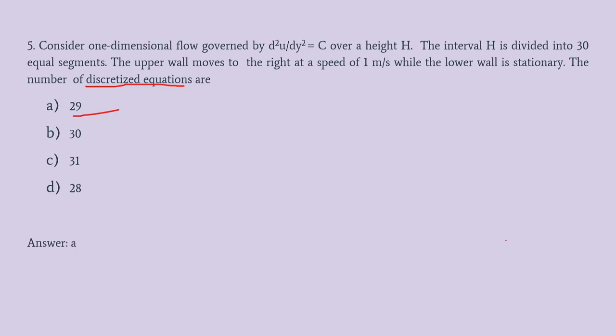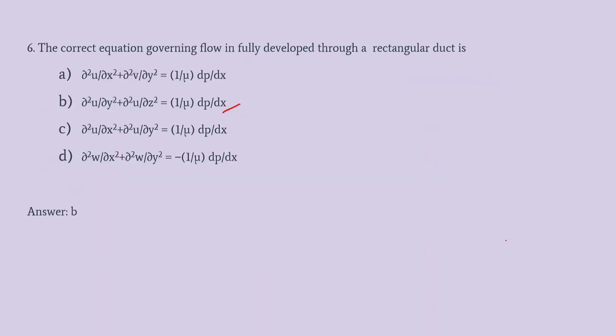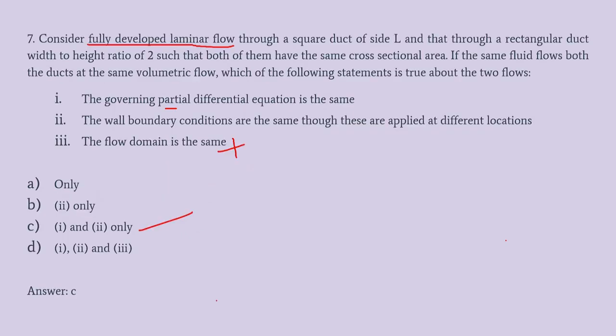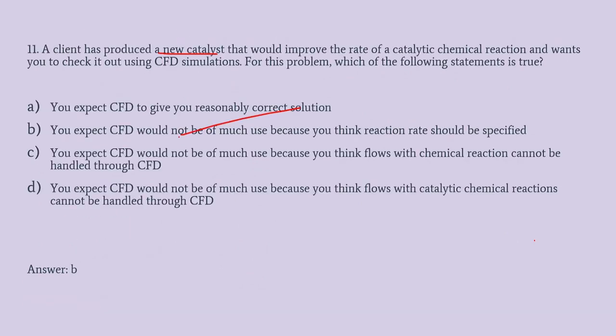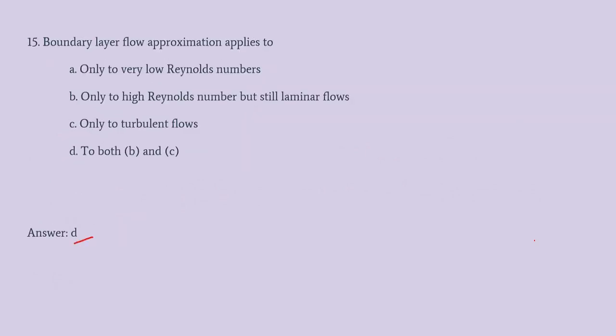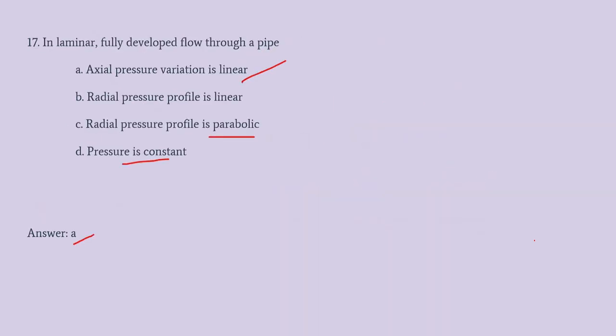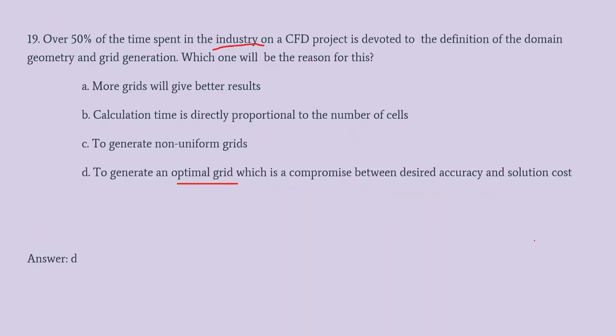So how to generate a mesh? What I have shown is an equally spaced structured mesh. You said triangular elements, or such elements, tetrahedral elements. There are different kinds of elements that can be used for meshing or discretizing. This is actually entirely a geometrical thing: how we are reducing the geometry to apply our approximation of equations. So meshing is one important thing where we are reducing the geometry.